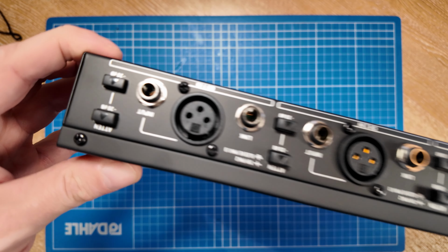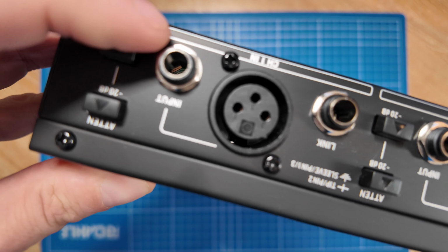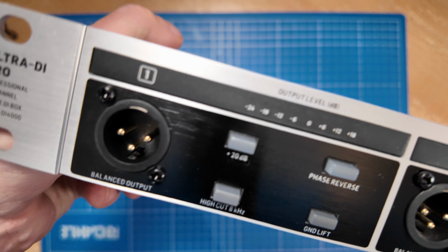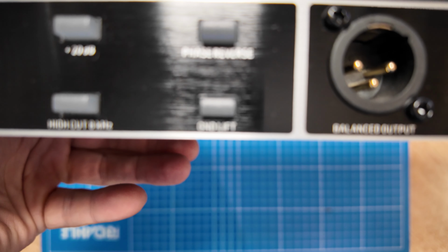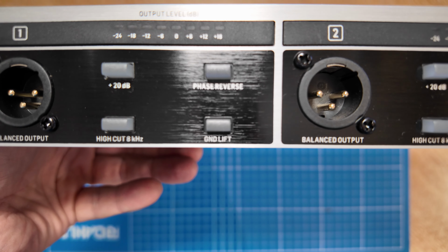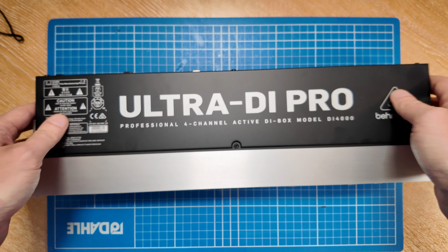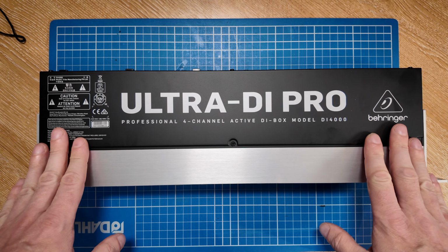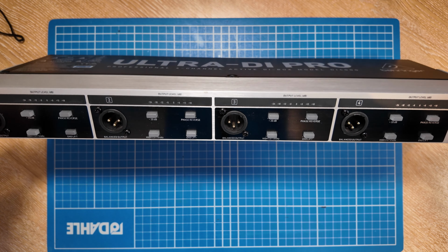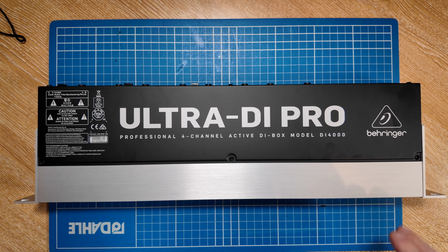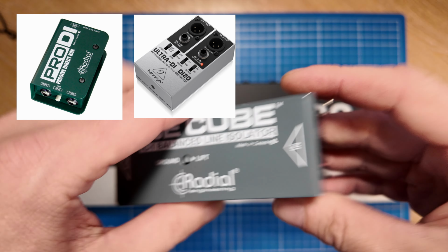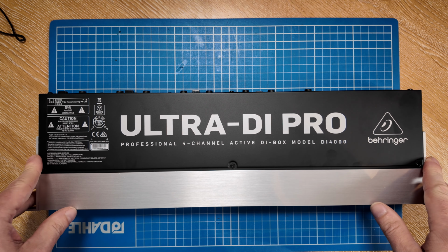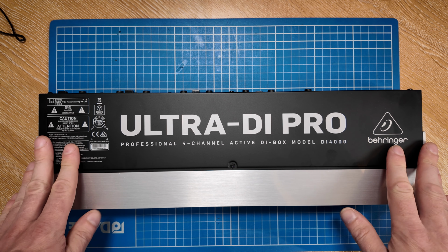And much like the line isolator, we have inputs on the back. This will take balanced or unbalanced inputs, and it gives us a balanced output on the front. And importantly, if my camera will focus, there we go, it also has the ground lift button, which is what we'll be using in order to break those ground loops. Now, you don't necessarily need something as large as this. A DI box you can also get in a small form factor like this. It's only because I happen to need 4 of them. There's 4 in the one chassis, and it just provides a nice way of mounting it for me. All right, let's head back over to the computer, and we'll take things from there.